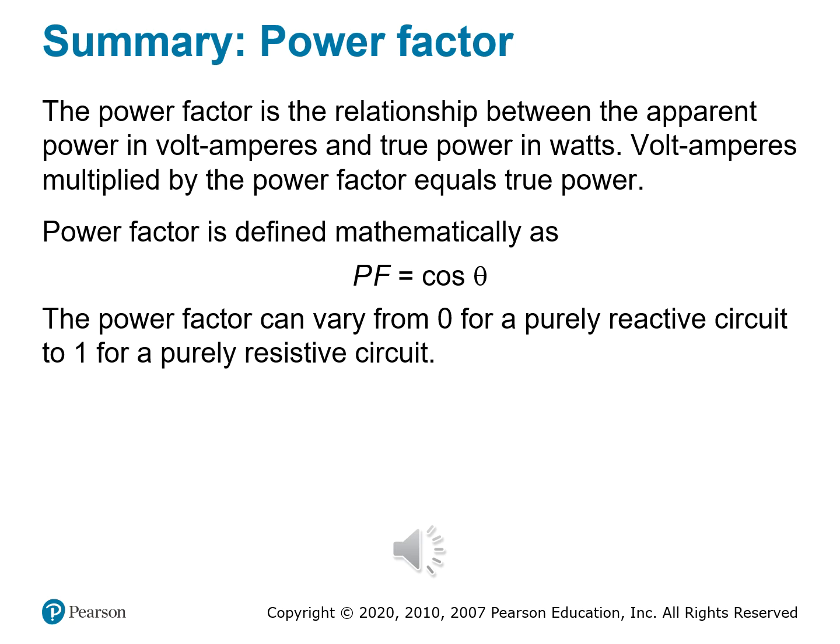The analogy is like imagine a horse that's pulling a cart. The more aligned the horse is with the direction of the cart, the more effective the pull. And that angle, that's your theta. So power factor tells how much of the horse's energy is actually moving the cart forward. And if we relate this to an RC circuit, especially at lower frequencies, the capacitor causes the current to lead, and that gives you a non-zero theta, and that means that your power factor drops.